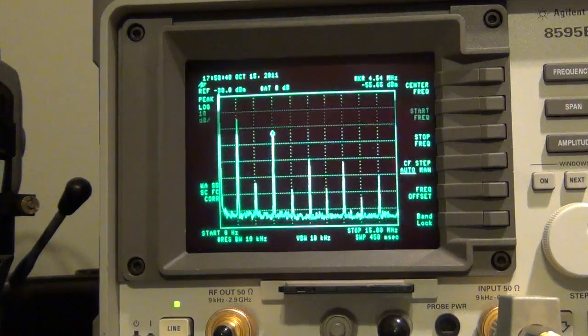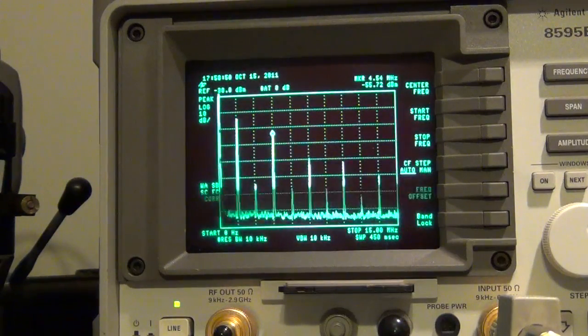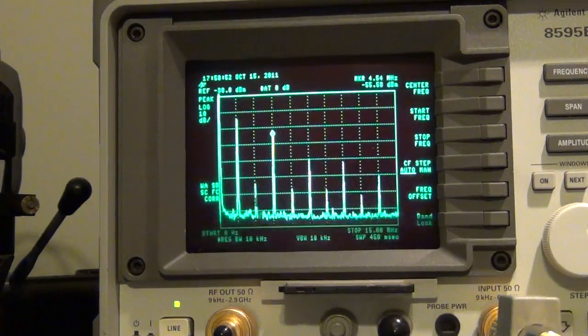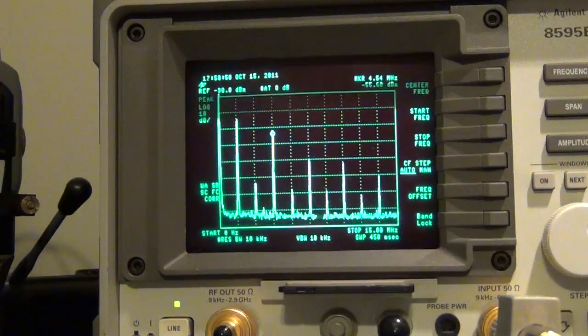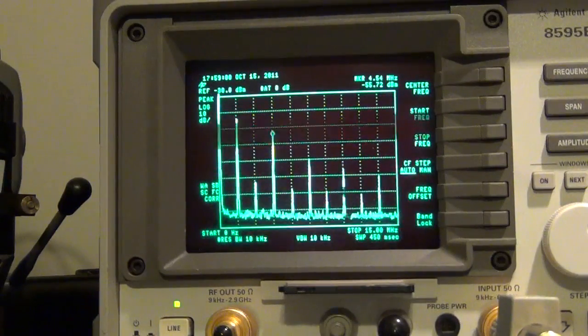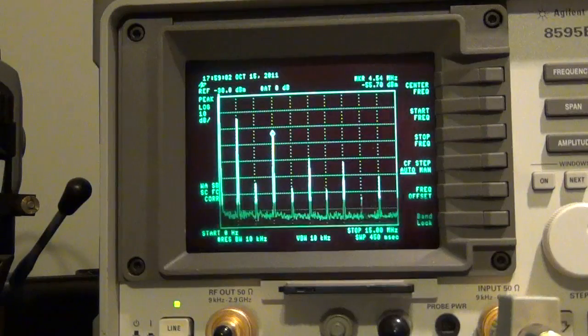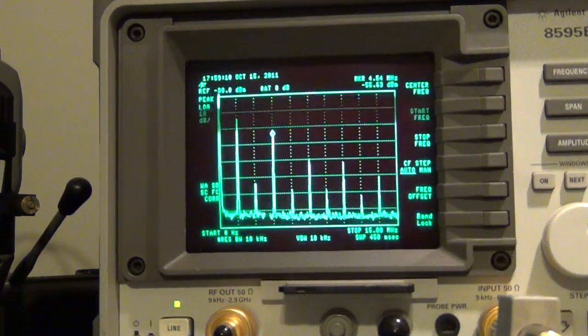Now what I'm going to do is I'm going to show you why this type of circuit is bad for wireless circuits. So I'm going to change the setup a little bit, then we'll talk about input compression, and we'll talk about the third order intercept point, and so on. So we learn how nonlinearity is actually measured besides just seeing it on the screen. So if you were to report the nonlinearity of a circuit, what is it that you have to report?